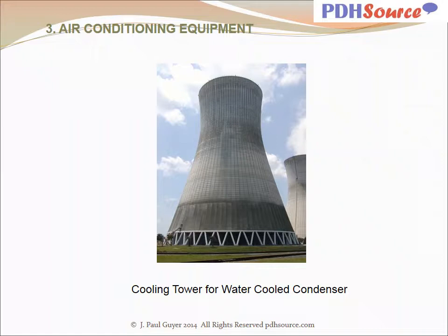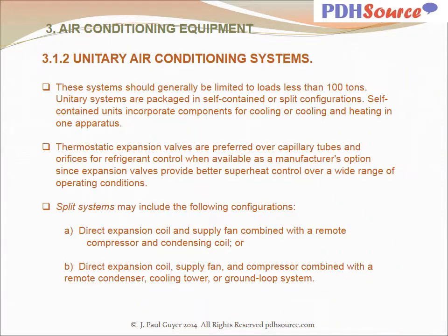So the air is drawn in at the bottom of the cooling tower and it rises and is exhausted through the top. That air draft mingles with the water as it is being sprayed, and as the water is falling down to the bottom, the air is moving upward, and this facilitates the mingling of the air and the water and the heat.